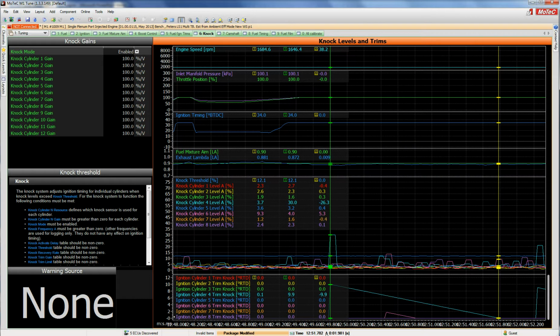Down here gives you the delta difference between these two cursors here. Just by pressing the space bar, I bring the beginning of the cursor, or the first point of the cursor, and now down here is the delta between the 2 points. So that's 1.97 seconds. If I got it exactly on the 2 points, that would tell me that it would be 2 seconds for our 10 degrees to decay out.